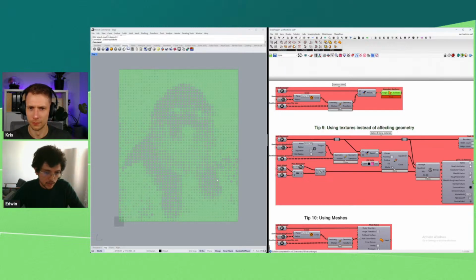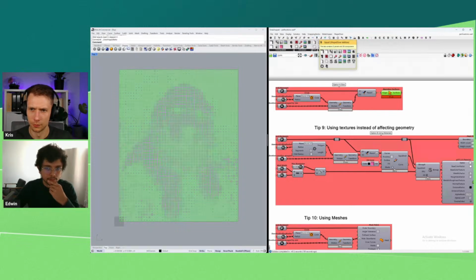So what is this hole? This hole is basically just transparency. In a texture, you have a material, you have many layers. You have the base texture map, you have the normal map, you have the roughness metallic map, and you also have an opacity map. These are just images, so JPEGs, that you can create parametrically as well through Grasshopper. There is a plugin called Squid. We have a version, ShapeDiver Edition, but there is also another version that is just Squid. And with that one, you can create parametric images.